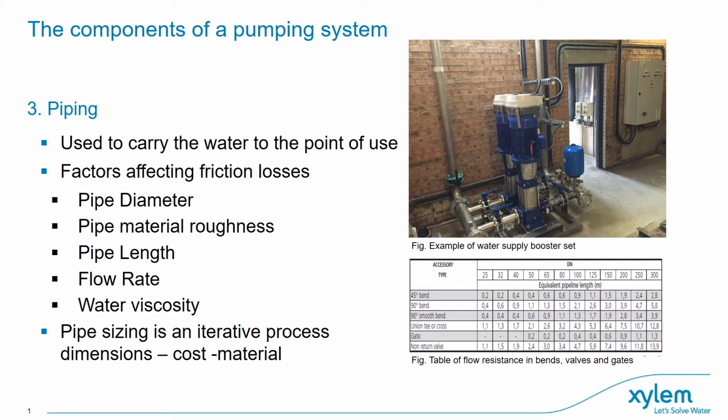Just to make some example, let's say at constant flow, bigger pipes are more difficult to route, but present less flow resistance at the same flow compared to smaller pipes, which in turn are much more flexible to route and to buy because they are less expensive, but at the same time might present much higher resistances and friction losses to the passage of the water itself.